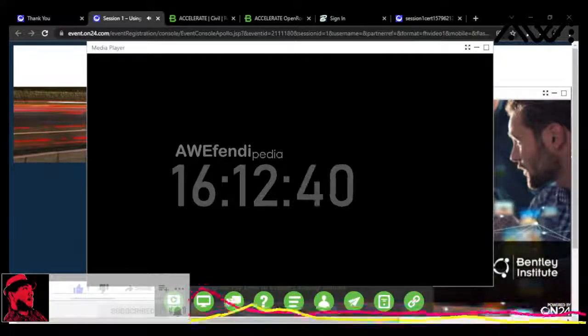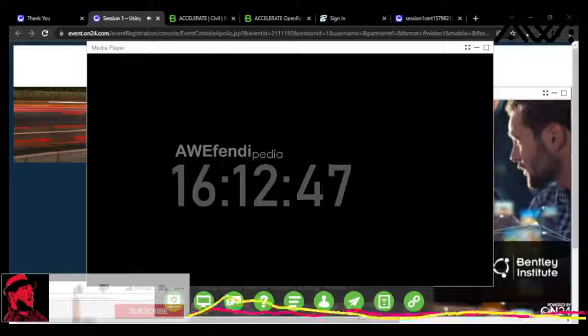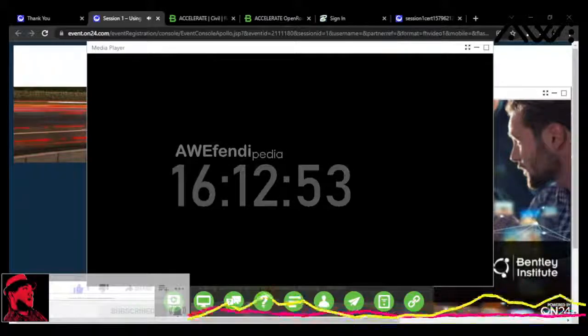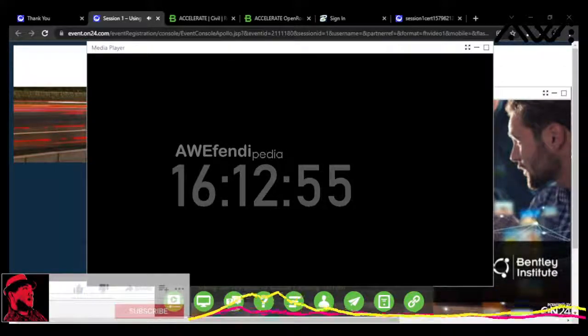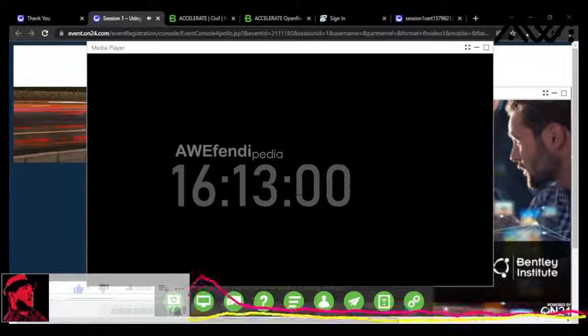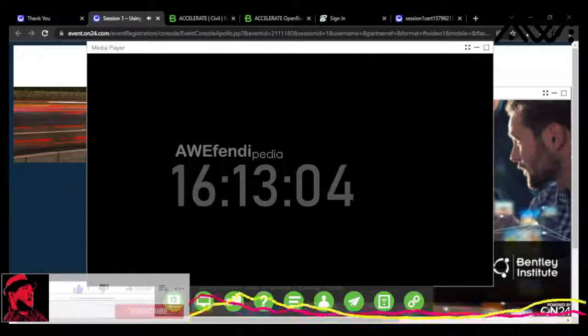We got a driveway drawn. We have a big spike over to the left, down at the bottom, near the left side of this project here. So what's happened here? Well, when the surveyor surveyed, we're coming into this driveway. When he surveyed the left side of the driveway, he called it DW1. And if you look at the tooltip here on the field code row, it has DW1.